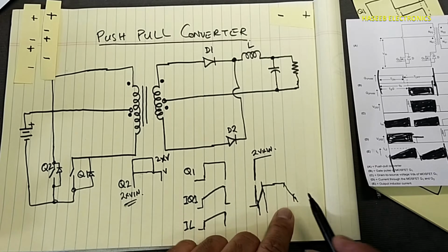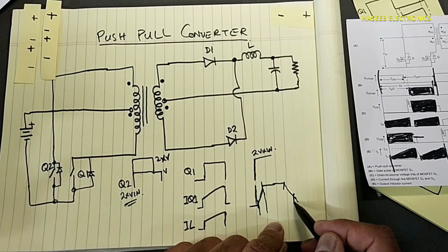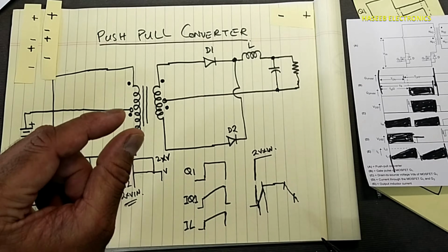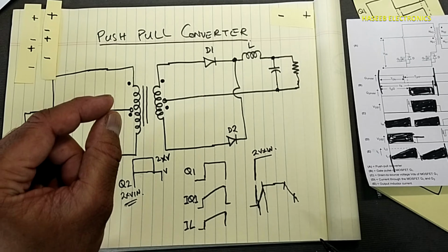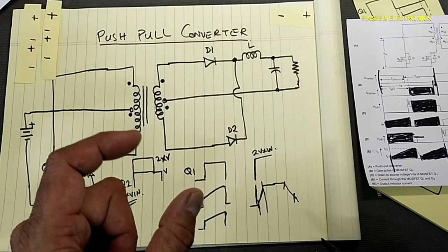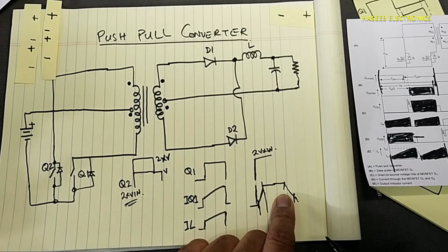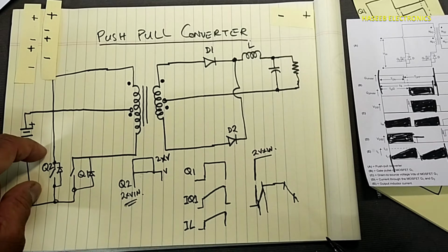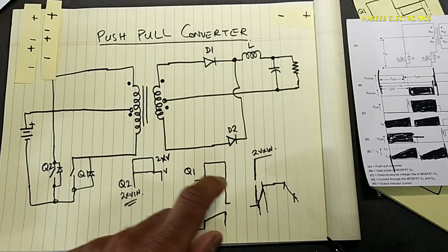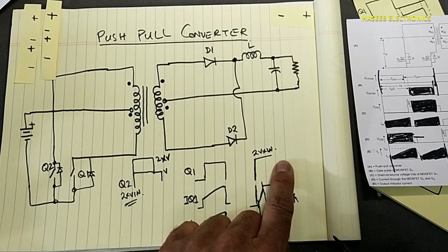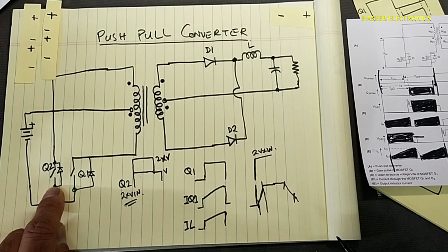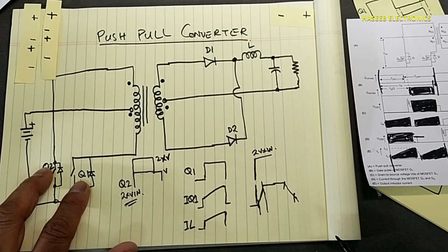But in this portion, when we are turning it off, its channel resistance will increase from low to infinity or high resistance. At that time it will dissipate power. Why? Because we have double voltage here. When we have more voltage, V times I will cause power dissipation. So this is the drawback of this topology.